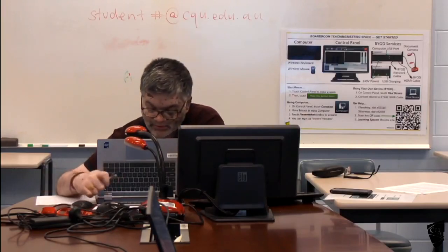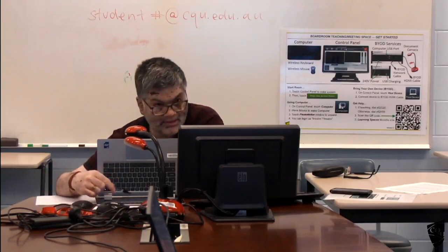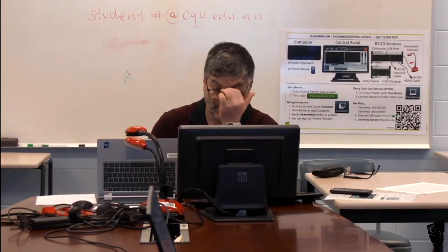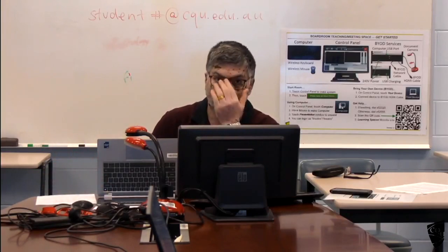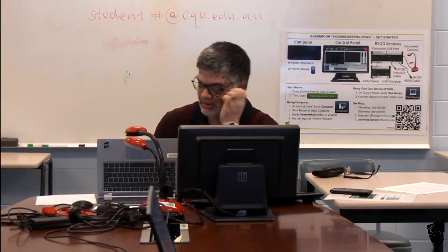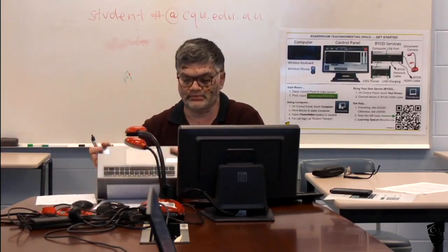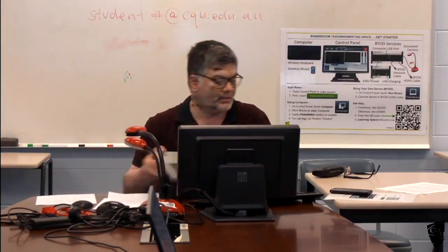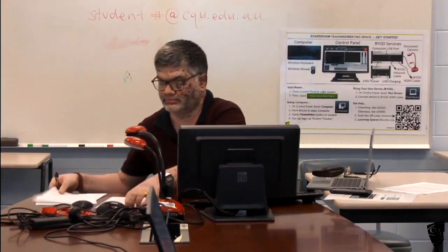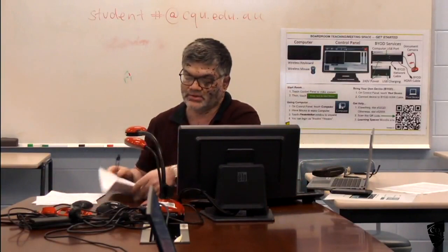And here the average is 0.6, so 60% will go to the column strip and 40% will go to the middle strip. That's how we distribute the bending moment. We calculated the bending moment from this one.